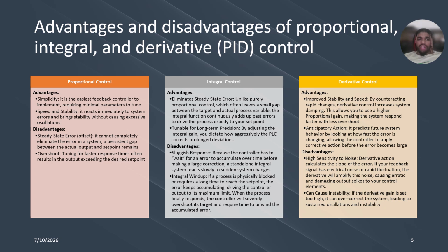Though some disadvantages would be steady state error or offset. It cannot completely eliminate the error in the system or persistent gap between the actual output and set points remains. Also, overshooting. Tuning for faster response times often results in the output exceeding the desired set point.